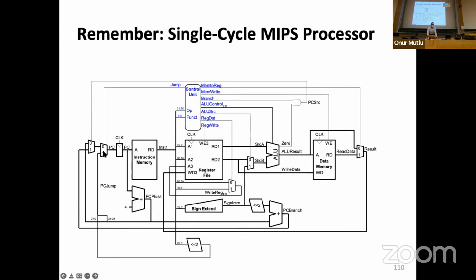And I'm going to use this other microarchitecture from your book, which is very similar to what we have constructed. You can see the PC source muxes over here. They were over here in the earlier design. You can see the input to the ALU mux over here. Oh, they put the mux over here. This is the mux that determines which destination register should get the data. This is the mem-to-reg mux over here. So basically, this is the single cycle processor we constructed.